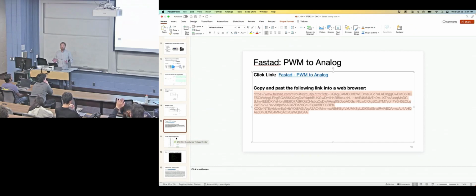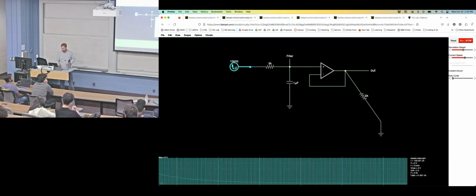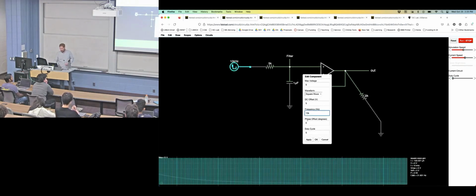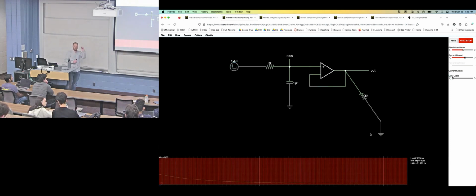Any other questions? Yeah. If we increase the frequency of the PWM, will that require more power? Yep. Every time you go from 1 to 0, essentially, some capacitor got filled or discharged. And so you can look at that voltage inside of the capacitance of that capacitor. Parasitic capacitance can be picofarads, and you've just wasted that energy. You've lost it. So that's the main source of loss, that and heat in your integrated circuits.